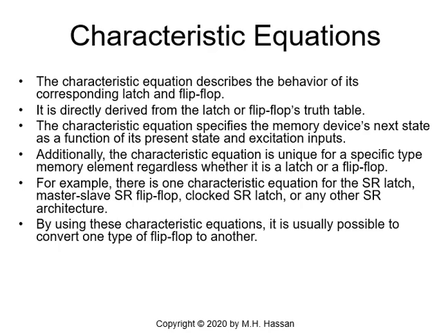Characteristic equations. A characteristic equation describes the behavior of the corresponding latch and flip-flop. It is directly derived from the latch or flip-flop truth table. The characteristic equation specifies the memory device's next state as a function of its present state and excitation inputs.